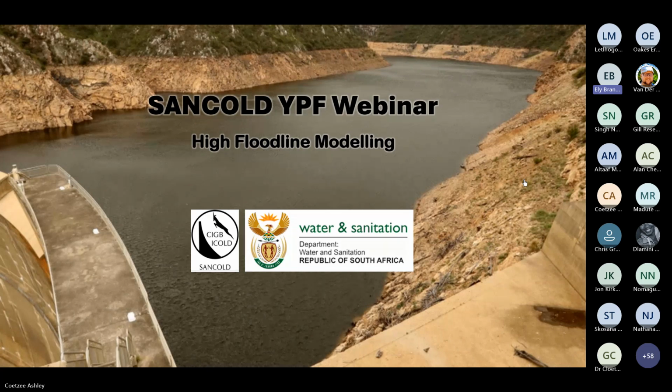Thank you, Kuku, for your questions. What was your first question again? It's how far downstream and upstream do you clip your contours for your model? If it matters, how far down do you go? Okay, usually for the high flood line of the dam, you're only interested in the area within the dam, so from where the river enters your dam up until your non-overspill crest level to your dam wall. But you can include a certain area downstream. It doesn't really matter how far downstream of the dam, just so that you can add extra cross sections downstream of your dam wall to allow HEC-RAS to produce a stable model.